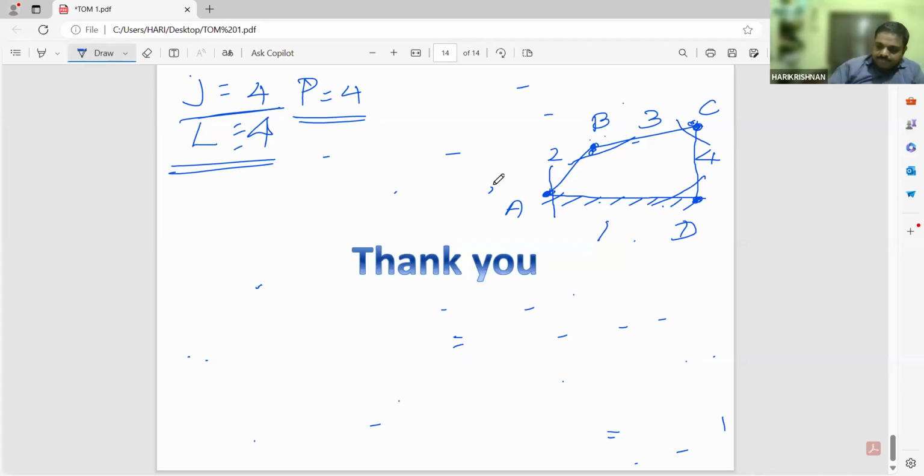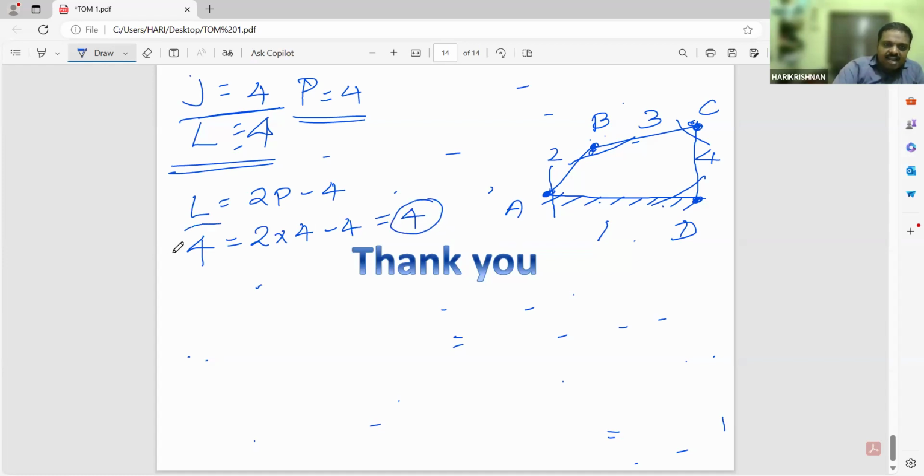So our equation is L is equal to 2p minus 4. The number of links is 4. 2 into the number of pairs, 4, minus 4. So 2 into 4 is 8, minus 4. This value is 4. So RHS is 4, LHS is also 4. So LHS equals RHS. Now the concept is clear. Any doubt?